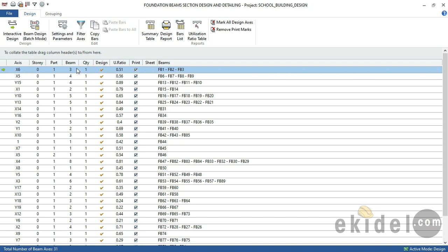Okay, so right now we can say that this first beam here has been designed, because we have checked it. That's why it is called interactive design, as you can see here. So you as a civil engineer, or a good structural engineer, are meant to check the software to see the kind of reinforcement the software used to design your members.